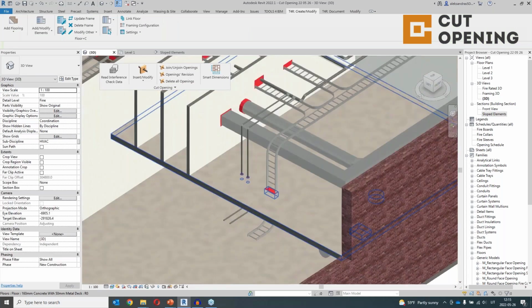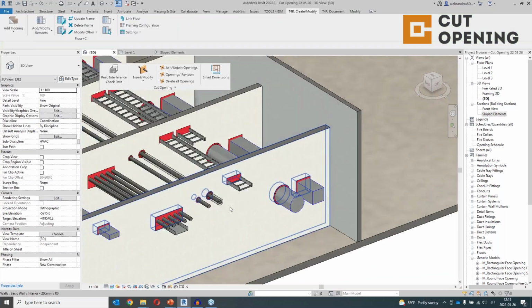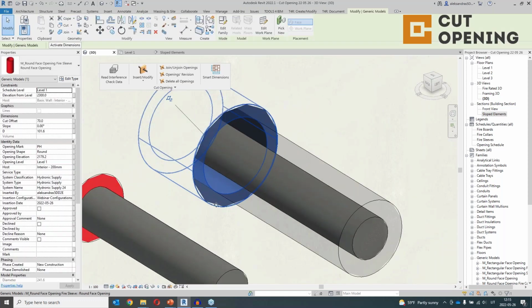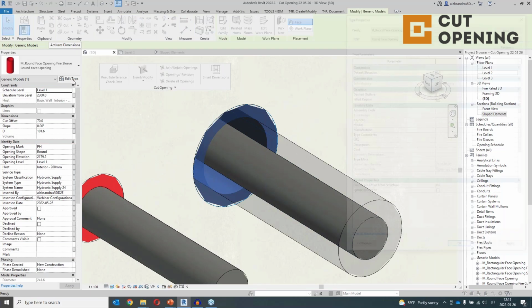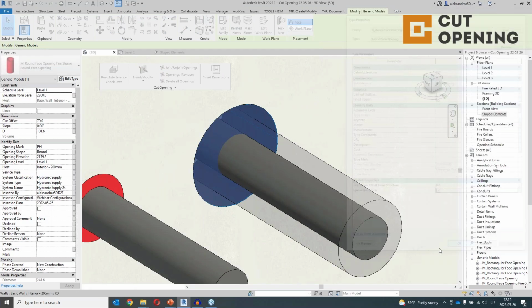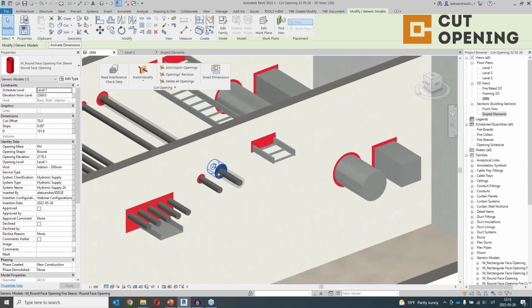And this is what we have. All the elements that were fire rated as 1 hour got fireboards and fire collars. And here you can see that the fire collar also goes around the insulation. Again, the same setting if it's needed. You can choose to ignore insulation completely, and the fire collar will be placed exactly around the pipe and fills in all the opening that was created, and that opening was created with a specific cut offset that was described in configuration.